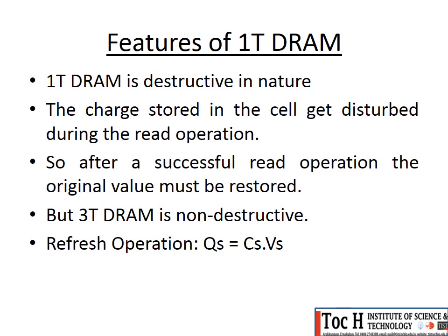So we need to refresh the data inside the capacitor in a periodic time of 1 to 4 milliseconds. After every 1 to 4 milliseconds, the data has to be read and rewritten into the cell. Okay, that is a feature of a dynamic RAM.